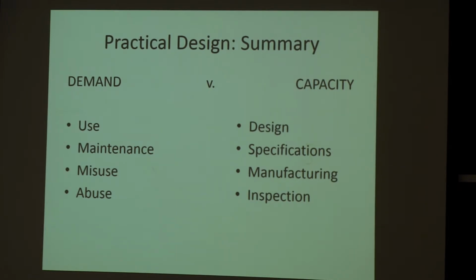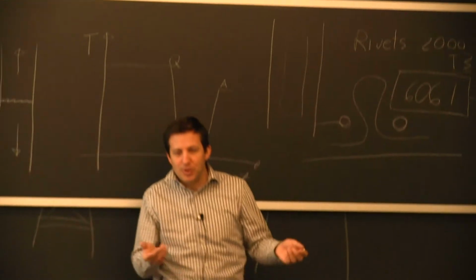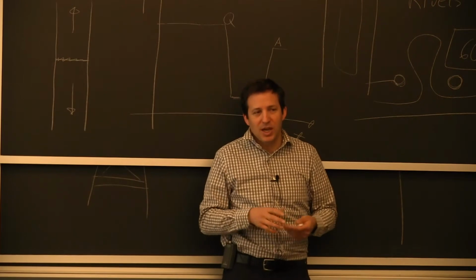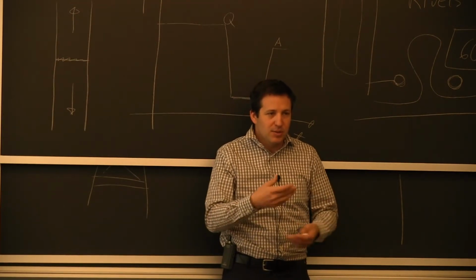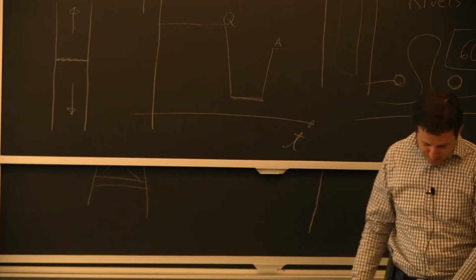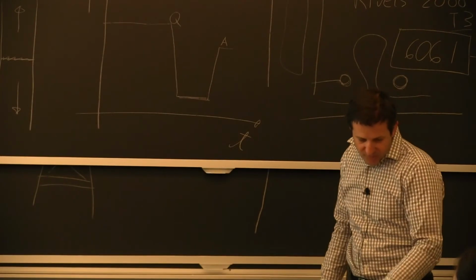It's not going up and down, just keeping it up. The environment enables the crack to continue. It's very specific to aluminum alloy and the presence of chloride with exposure to the sea mist. But that industry has to take that into account. If you're working with a steel frame in automotive, it's different. Now you worry about, if the primer is not good, we're starting to have some pitting corrosion, and I have to deal with some aspect with the underneath structure. I'm talking about the main frame, not the body itself. But everything is specific.